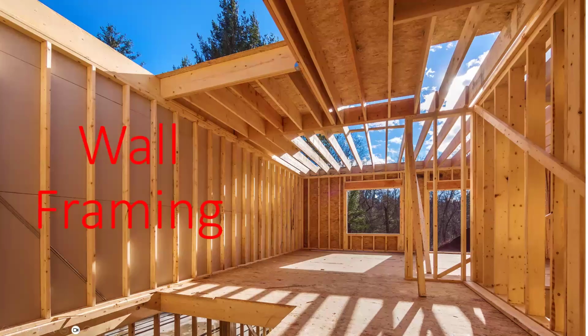What happens if the wind's blowing towards us from like the forest out there is that this wall has to have lateral bracing. Now, the reason I like this photo is you can tell this is a townhouse, right? Where it's like a row house, if it was the outside wall, they would put the OSB on it, but it's not. It's got to be a firewall probably between the units. So they've got a layer of gypsum board running between it.